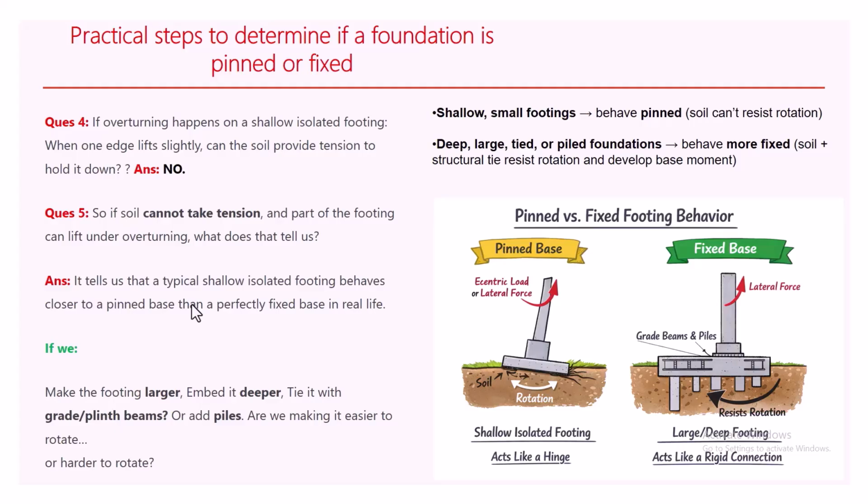You can also have your footing partially fixed because when doing construction, we normally have what we call the backfill, and we also have the surrounding soils around your structure. That means your structure is buried into the ground. So you see that at some point it is partially fixed, not completely pinned, even though it is an isolated footing. But in a conservative design, we try to assume that your isolated footing is pin supported.